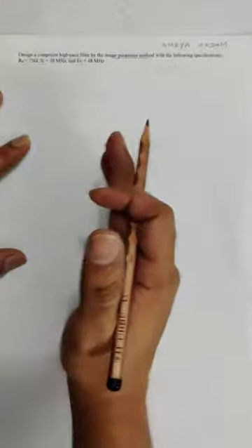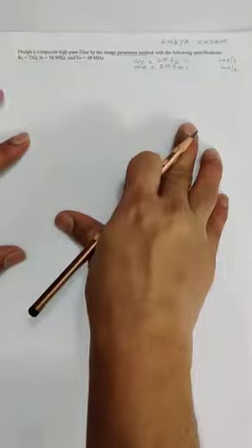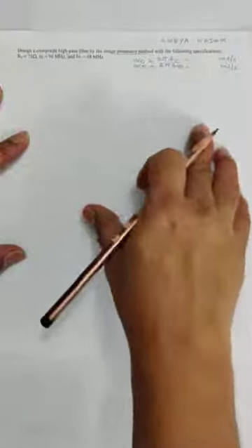You have a matching section at the input side and another one at the output side, and we have the constant K and M derived sections. So first we'll write the formula for omega C. Omega C is 2 pi Fc, and omega infinity will be 2 pi F infinity. They will be in radian per second. Now first we'll design the composite constant K T section network.